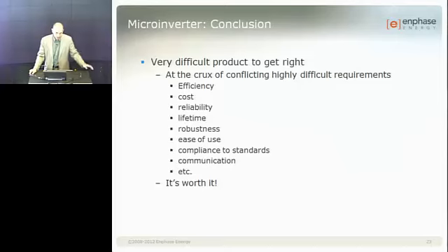That's fairly old now, but it was an OFDM-based transmission system, orthogonal frequency division multiplex. The problem in that system is that they had to transmit a lot of energy across the band, but they were also constrained by the noise floor of the power line in that band. So they had to inject quite a bit of power to be above the noise floor that they expected.